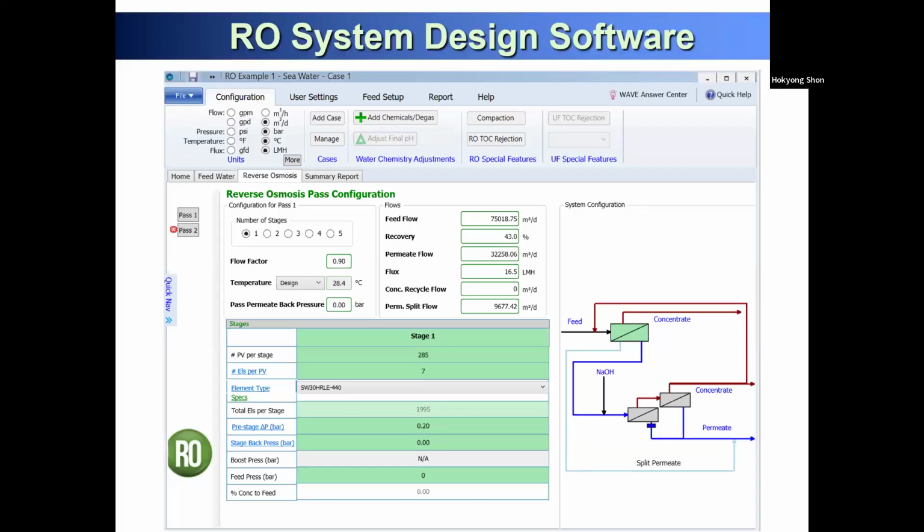But the problem is that when you operate a new membrane, for the first month your performance is 100%. But after 1 year, your membrane is aging, fouling and being damaged. So your membrane performance after 1 year is potentially reduced by 10%.